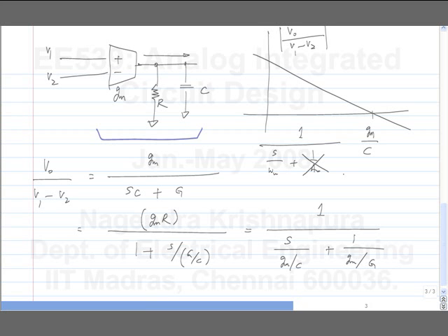Okay. So we clearly see that we cannot make infinite DC gain because every transconductor that we have seen so far has a finite output resistance. Is this okay? So we try to make this. We know that we have transconductors, we also have capacitors, so we can make an integrator this way, but we'll always end up with some resistance. So this is why we'll have a finite DC gain. So we'll design some Opamp and see that this in fact is true.